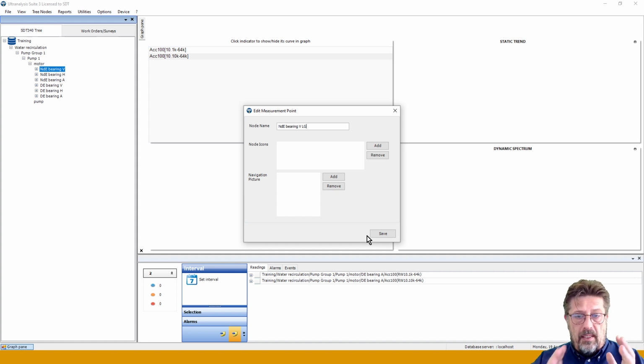So I can say, show me all the motors which do not have sealed bearings. They are lubricated with grease, and I can extract them out and take a look. There can be a million reasons for that, but one of the reasons can be, yes, we are doing great condition monitoring, but it seems that we have a lot of problems on grease lubricated bearings, so let's talk to the lube team. That's one of the options.